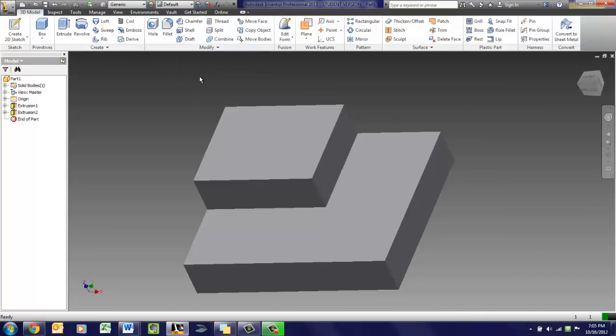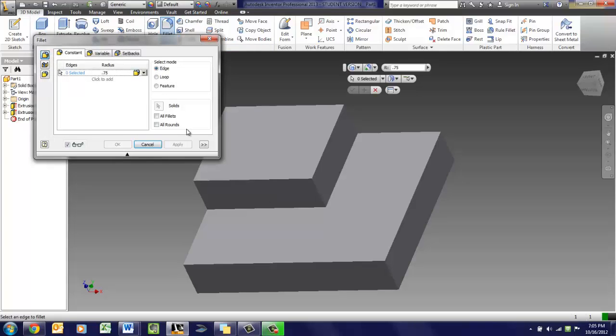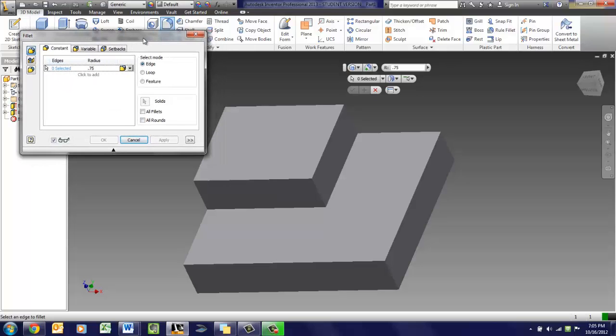We're going to find the fillet in this 3D mode under Modify, within the Modify portion of the ribbon. So click on Fillet, and as you can see, a dialog box comes up. We also, like most things, have a dialog box over here that gives more explanation. Then we have the quick pick over here on the right hand side. Let's start with the dialog box first to get used to things. The setting usually will be constant. It's a constant radius fillet or round.